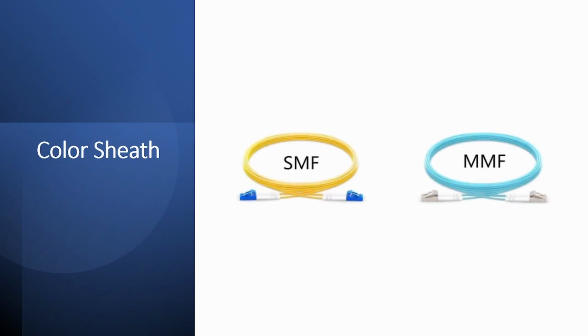The other difference is in the color of the single mode and multimode fibers. According to the TIA 598C standard definition, for non-military applications, single mode cable is coated with a yellow outer sheath and multimode fiber is coated with an orange or aqua jacket.